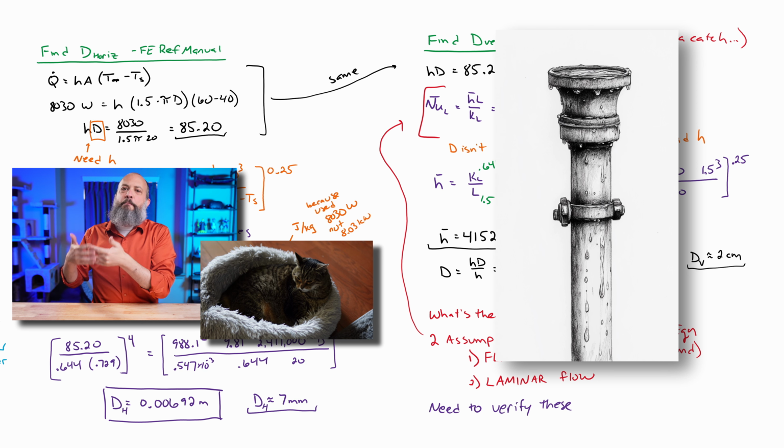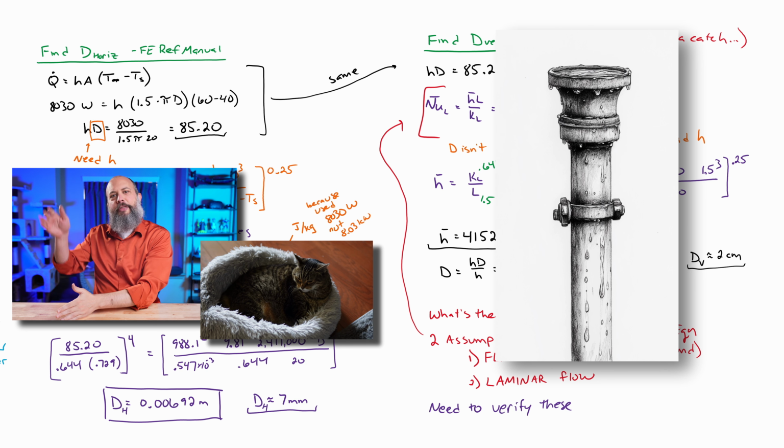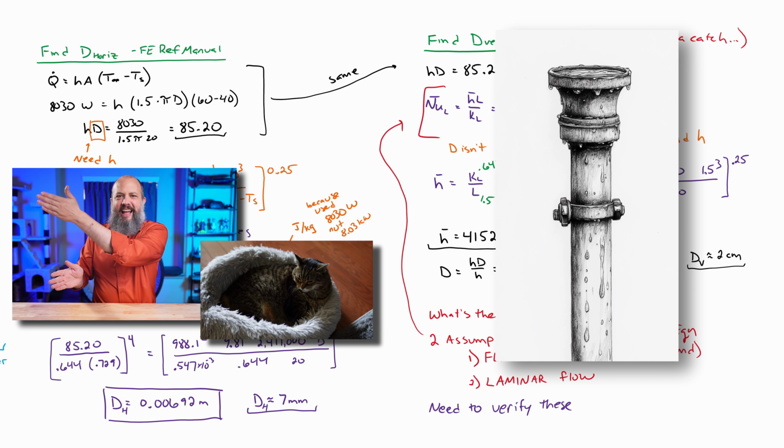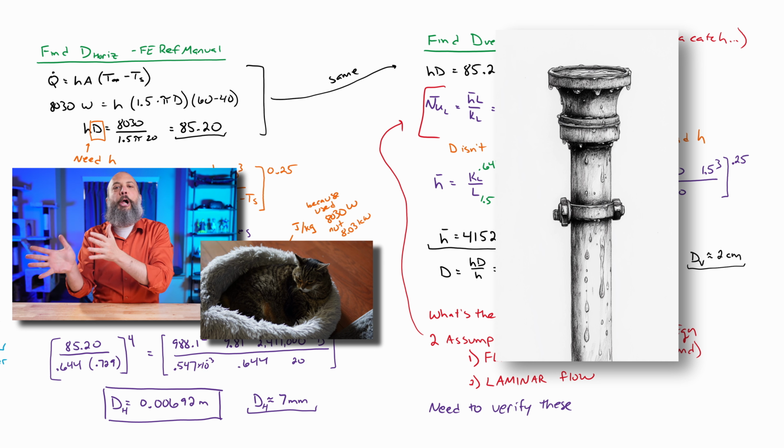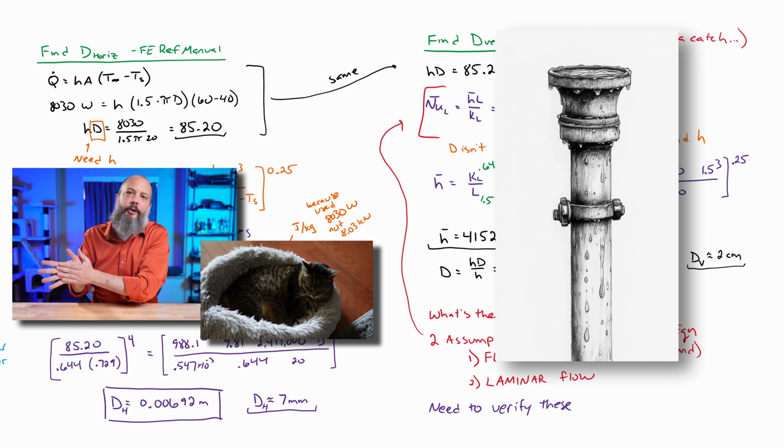But if you get more condensation happening, the first transition you'll get is to wavy laminar flow, where you have so much water flowing that it's still smooth, but there are ripples on the flow as it moves downwards. These ripples allow the water to flow horizontally, from further away from the wall to closer to the wall, and that helps heat transfer. It increases heat transfer more than regular laminar flow.